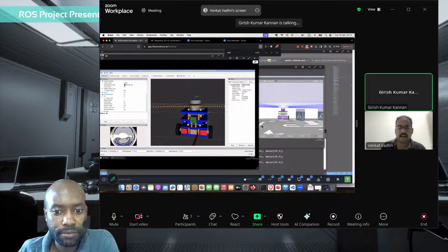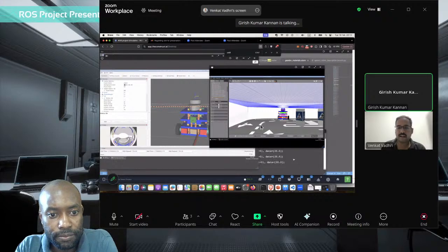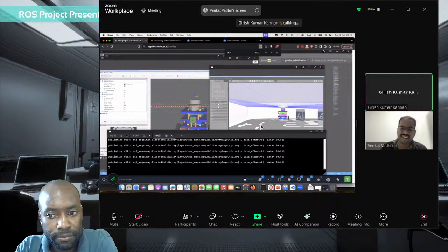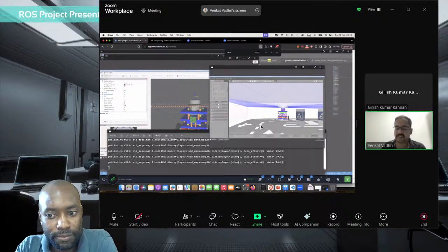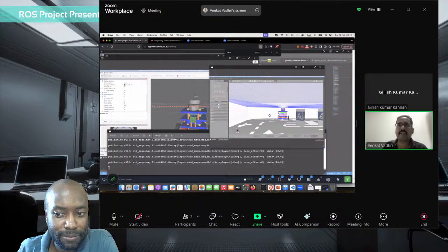Okay, and a quick question about that. I saw your Xacro files containing inertial values as bigger decimals. Did you not find time to have a macro for that one, to specify inertials? No, I didn't find a macro. I'm sorry, I didn't find time to replace those. When I ran it, it didn't do any harm, and I left it there. It did cross my mind that I should empty the entire inertia files when I moved to the real robot, but I didn't find time. It's a matter of time.